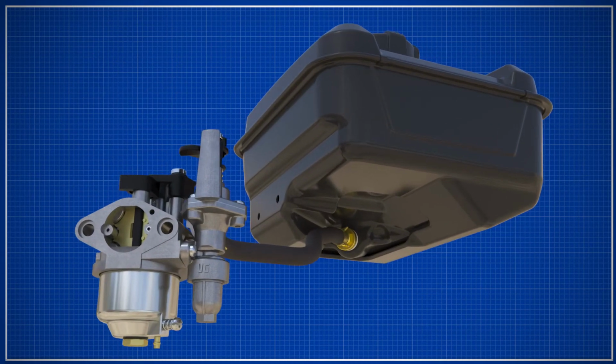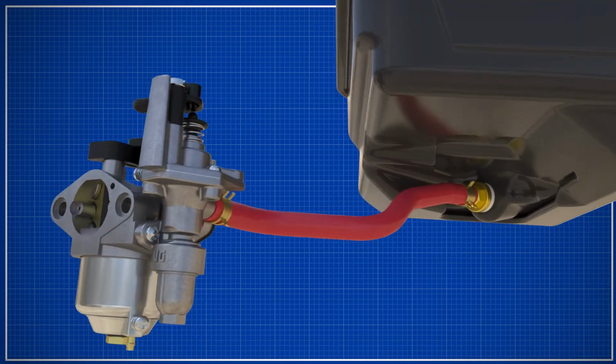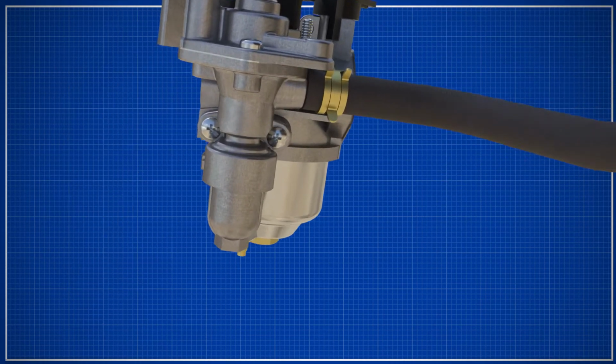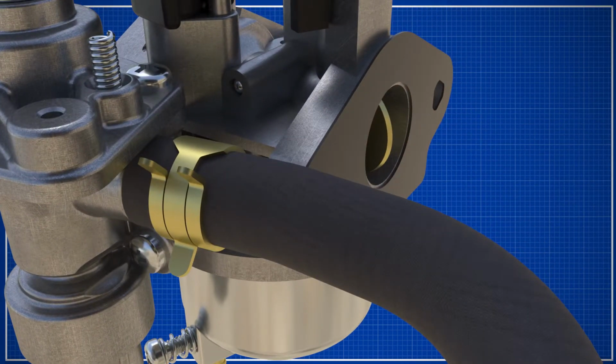Fuel inlet controls. In order to give sustained engine operation, it is necessary to keep a continuous supply of fuel in the carburetor. Fuel will be supplied from a remote containment source. A fuel tank is attached to the equipment or directly to the engine. A fuel line will move the fuel from the tank to the carburetor body. Frequently, a fuel shutoff valve is put between the fuel tank and the carburetor. This valve stops the fuel flow for transportation or during long-term storage.